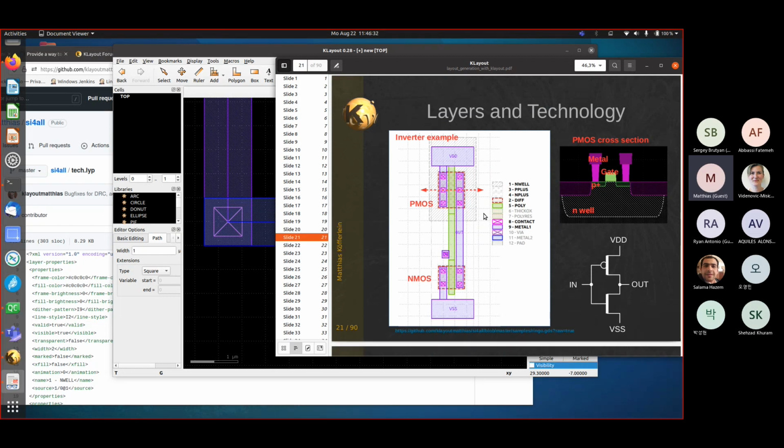It's only a partial PDK. I think they have added only the absolutely necessary design rules. But when you design in advanced nodes, 20 nanometer or something like that, or even FinFET, you may have more than 5,000 different design rules to comply with. And you need a tool to check this. You cannot do it manually.